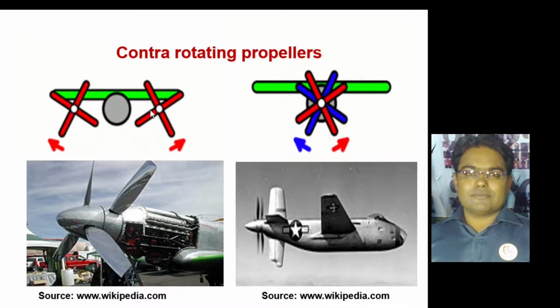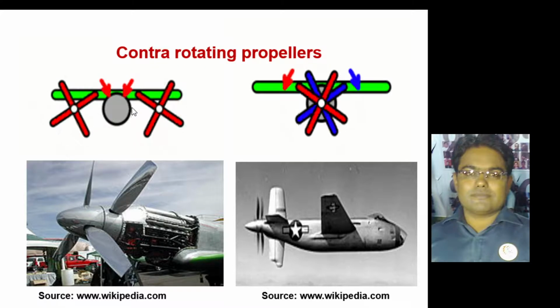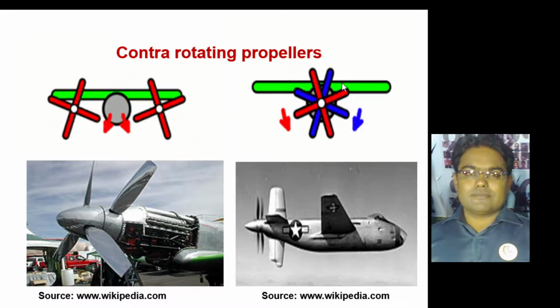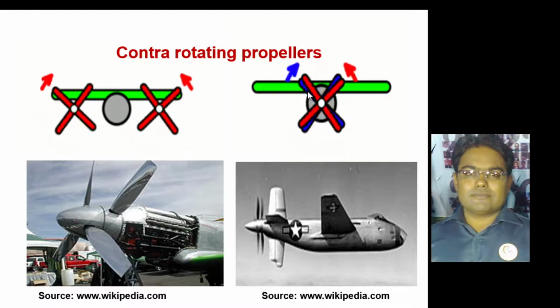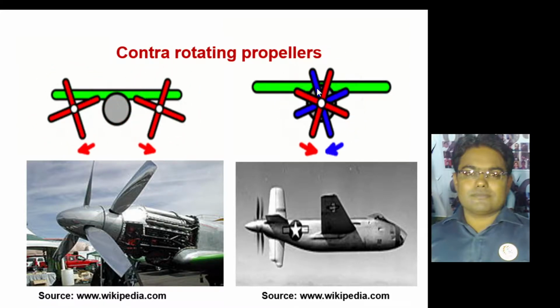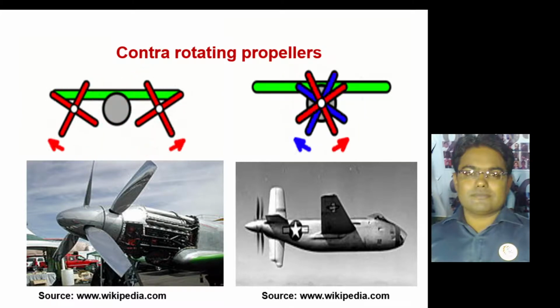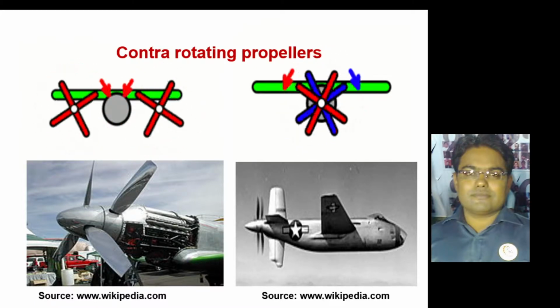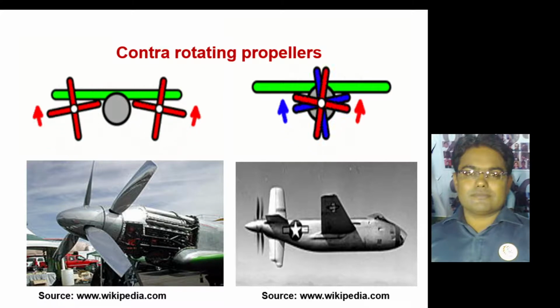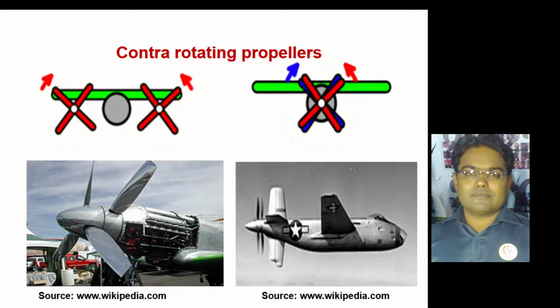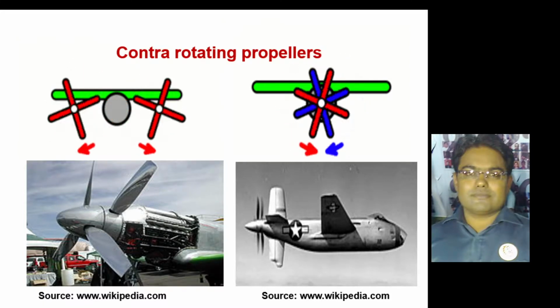Either there may be two propellers attached in two different directions, or there will be a combination of propellers on a single hub. If only one aircraft engine is being used, especially for general aviation aircraft, it will have two pairs of propellers. One row of blades will be rotating clockwise and the other anti-clockwise.